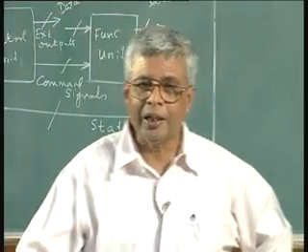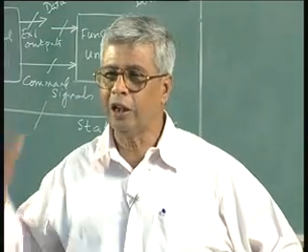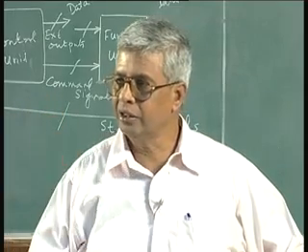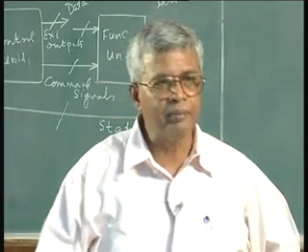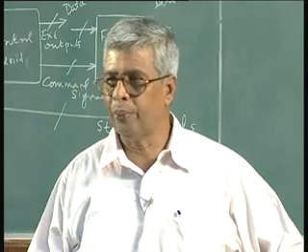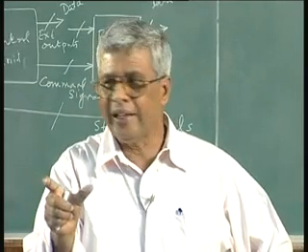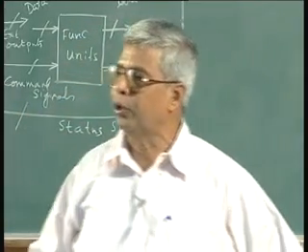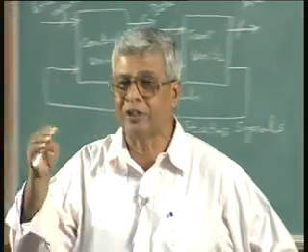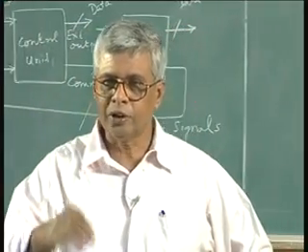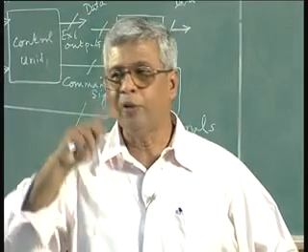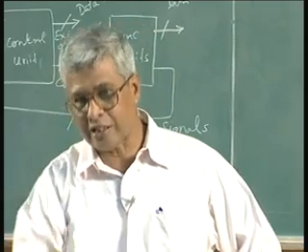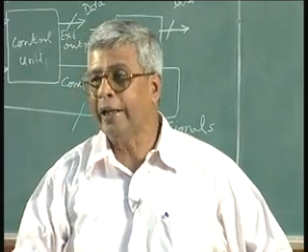As long as input A and B are there, output is there immediately, and we are talking about clocks which are slower, and those combinational delays are very small, nanoseconds delays, correct? Combinational delays are nanoseconds, whereas clocks depending on the frequency of operation will have much larger periods. So, it is not going to wait for you to give an add signal. As soon as A and B are given, it is going to give an output. So, now I want to control it when I want to add. I can only add after shift or shift after add, whatever. So, some sort of a control is required. Then I think, okay, maybe a 4 bit full adder is all right, but something else has to be there. So, a 4 bit adder can feed into a register, and the output register can be controlled. I can load it when I want to add it.